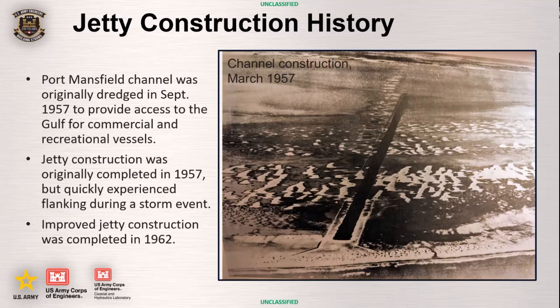One thing I want to point out with this slide and this aerial image, and I really like it, is that it's taken from an older USACE report format. If you look on this image, you can see these white squiggly sedimentary bodies. Those are transverse barchanoidal dunes. As an aeolian geomorphologist, I can look at this image and tell there's a lot of sand in the system on one hand. And secondly, there's a lot of wind driving that sediment across the landscape, right?